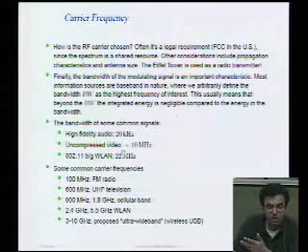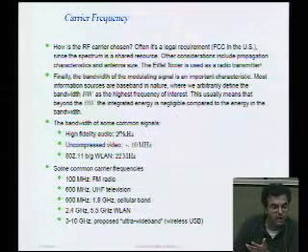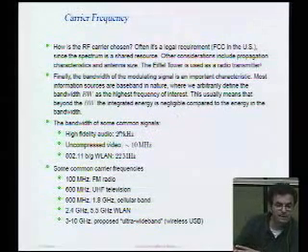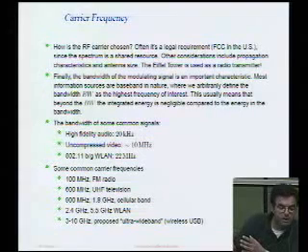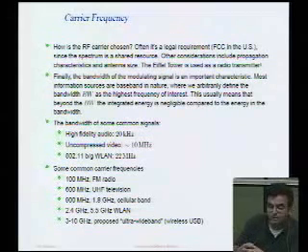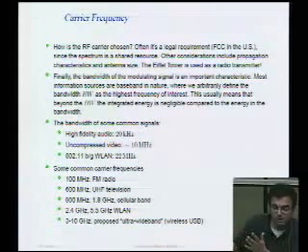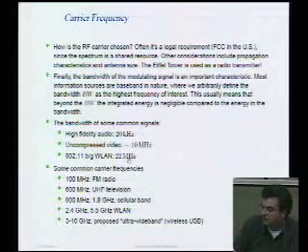High fidelity audio is about 20 kilohertz of raw bandwidth. Now, if you modulate that linearly onto a carrier, the bandwidth doesn't change. So if I just AM modulate, bandwidth's about the same. If I do some kind of nonlinear modulation like FM, there's actually a big bandwidth expansion. I need about 10 times more bandwidth.